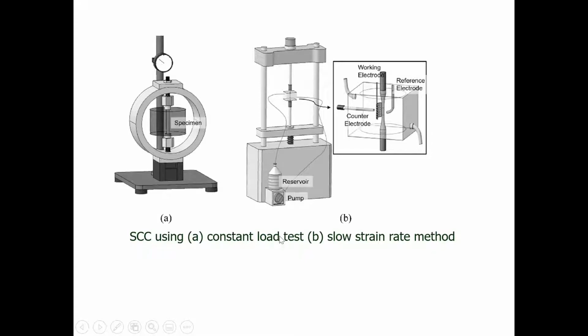So a constant load test will give a result. But the problem with this test is we don't know how long to wait. It could take weeks for it to break, or it could happen in a few days, depending on what material it is. So that's this test.